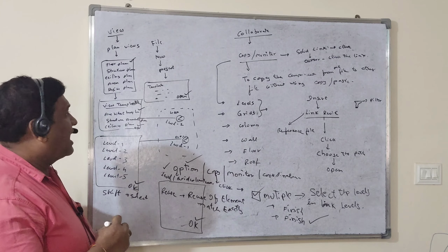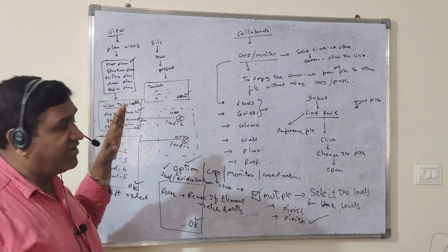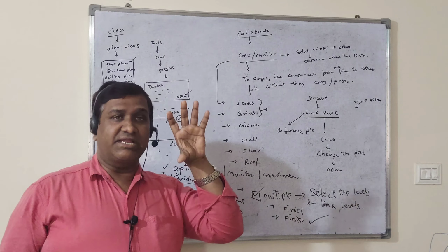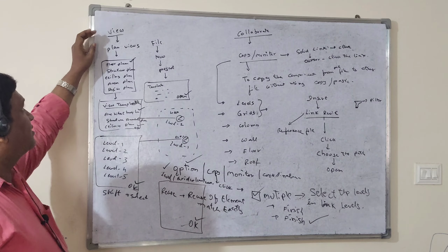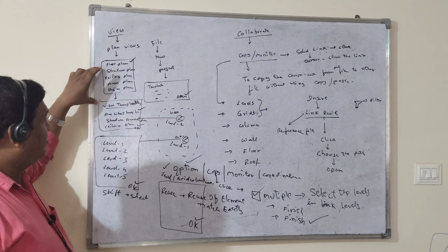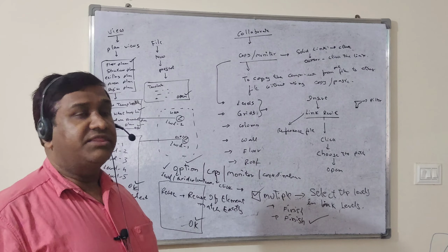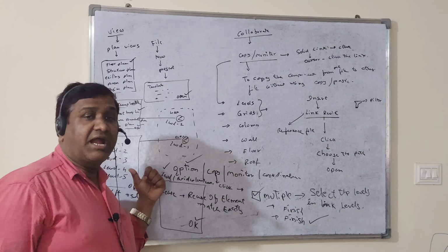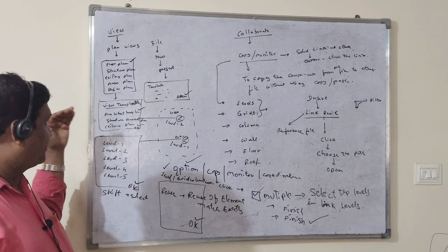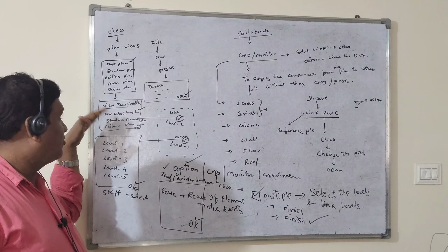So like that, after making the copy monitor, whatever levels you have made copy monitor, we have to use those levels with the assignment of view, plan views, and here you have to assign the view templates. With the help of view templates only, this architecture, structure, ceiling or MEP, if you are working with MEP, you also have to go to the template.